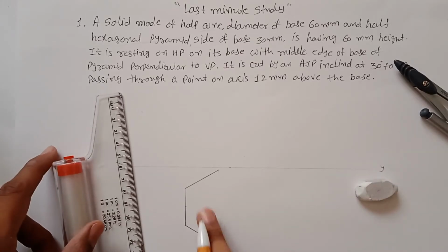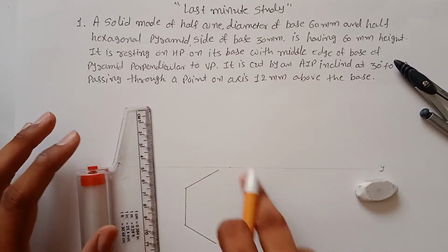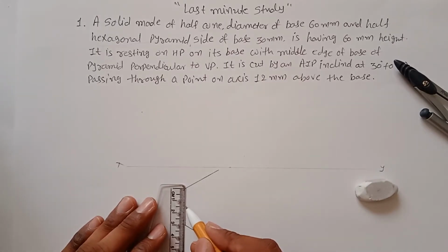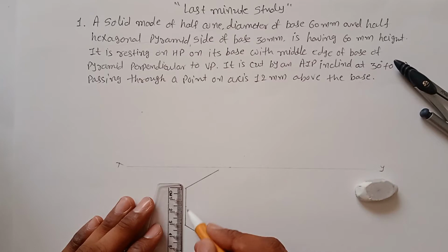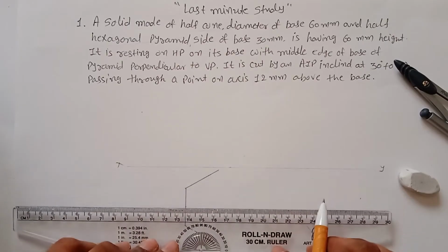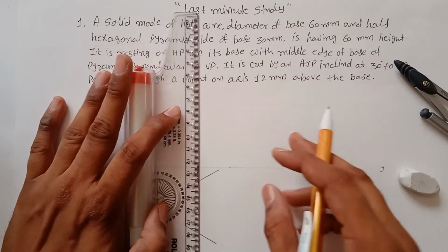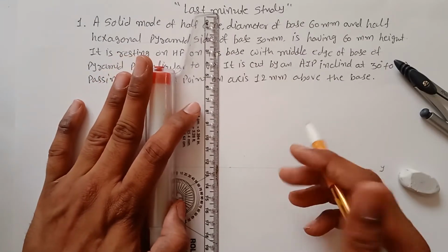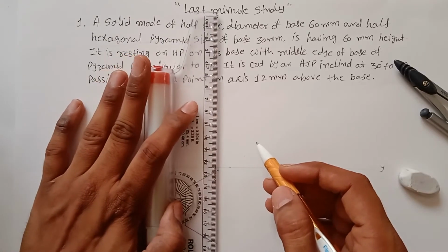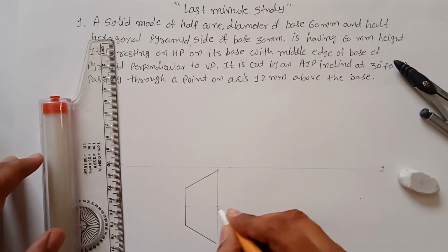This is the half hexagon. To draw the cone, in the cone the top view will be a circle, so here a half circle will be there. So for that, find out the center point of this side, which is 1.5, because the height is 3 centimeter. Draw a horizontal line from this point, a very light line, because you need to find out the center point of the circle, and draw vertical lines from these two corners. So this is your center point.